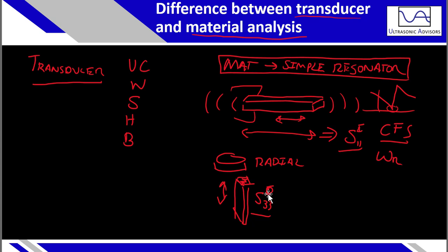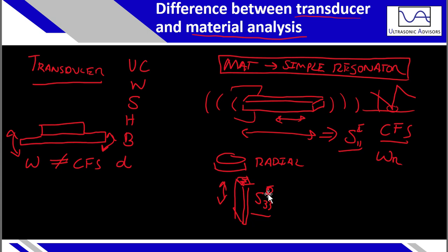Now, if you look at a transducer, let's just take a piezoelectric bender, which has the piezo material on top and another passive material on bottom, and when it's excited, there's bending motion. The resonant frequencies here will not have a closed form solution relating to the different material properties, such as the piezoelectric charge coefficient or the piezoelectric stiffness or the compliance.